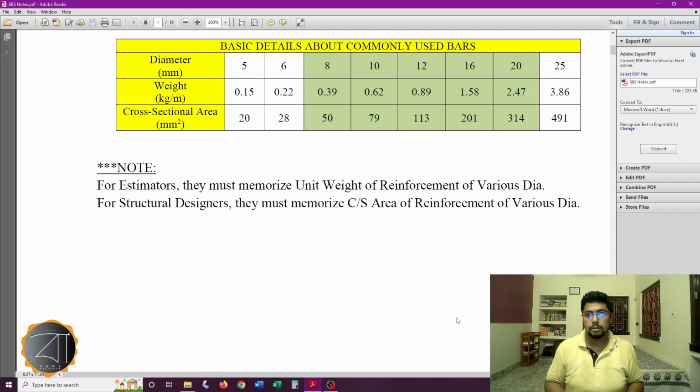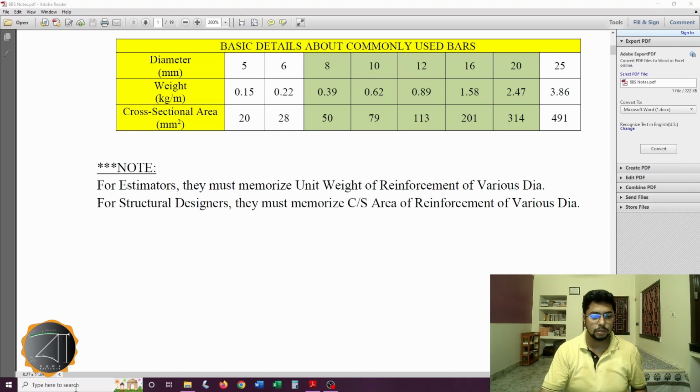But though as a structural engineer we know some reinforcement shall continue through the bottom, we are not at all bothered about the provision of the bars which are used to keep the crank portion or the top mesh, if we are providing the top mesh separately, in its proper position by providing the chair, what we know as forming a bar into the shape of a chair. I'm just trying to show how it looks.